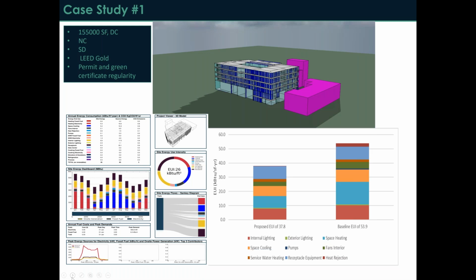So one of the things that energy modeling was helping the designers and architects with was how to decide about the fins and the glass type. If you see on a facade, there are specific fins and a specific facade design that, if architects wanted to decide themselves without doing energy modeling, was unachievable without consulting with the energy modeling.